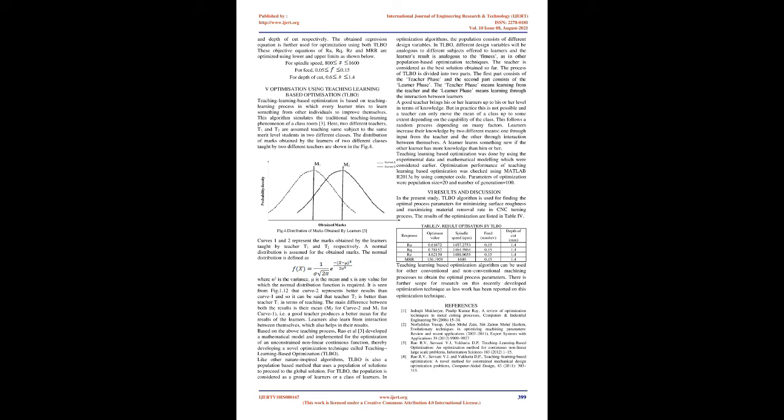20 specimens of same dimensions are prepared first. After that, the weight of each specimen is measured using a digital balance meter. Then the specimen is turned at different speed, feed, and depth of cut according to the design of experiment. Again, the weight is measured for finding the material removal rate. After that, the roughness parameters are measured using surface roughness tester SJ210. Roughness parameters Ra, Rq, Rz are measured for each specimen at 3 different locations and the average value is taken. Data collected are shown in Table 3.